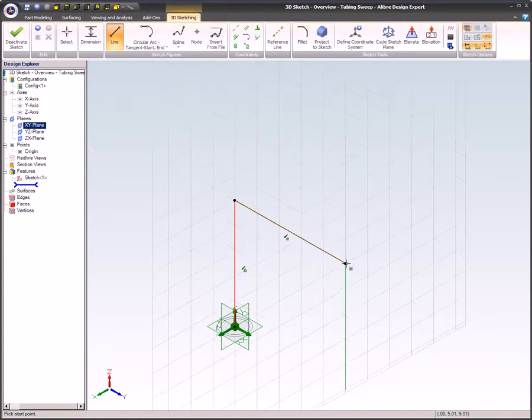After creating a horizontal segment from the end of the vertical line, the F key is pressed once to cycle to the ZX plane where a couple more segments are created. Here's a tip. To change the elevation on the current plane, hold down the letter E while moving the mouse cursor. You can start drawing a line at one elevation, and then press E while placing the other end of the line to achieve a diagonal line between the 2 different elevations.